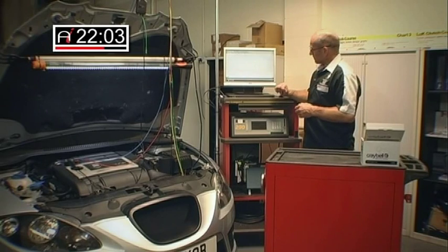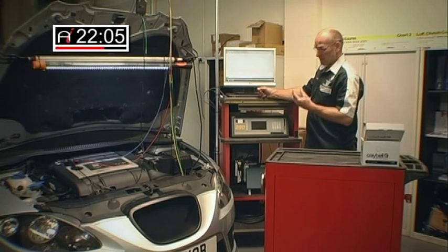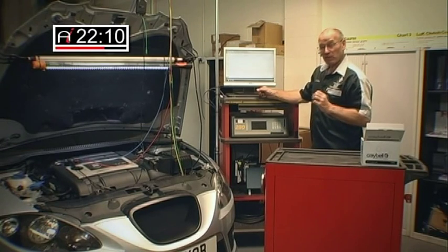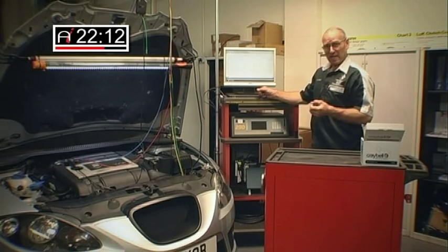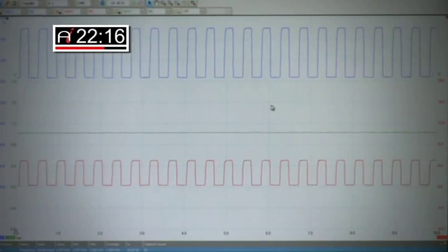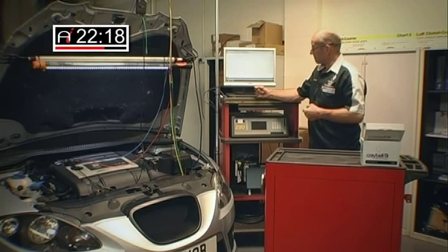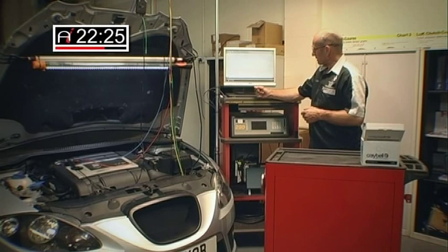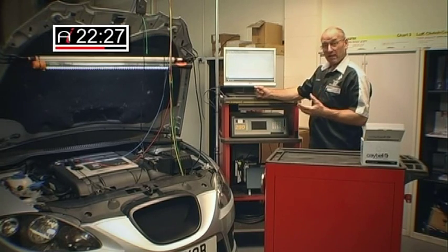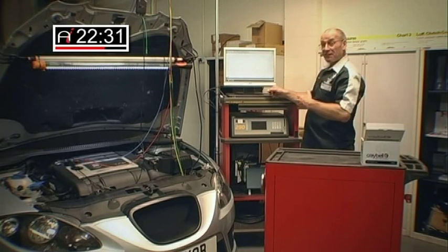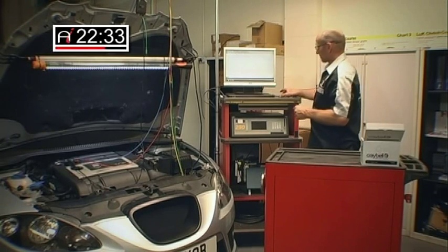Now the problem is, if I want to look at this air mass meter historically over a trend over several seconds, and I normally use 20-50 seconds of real time, I can't view a frequency, nor can the oscilloscope calculate a frequency for me, nor can it show trend. So I need to go back to my original setting and now apply a 50-second time base.